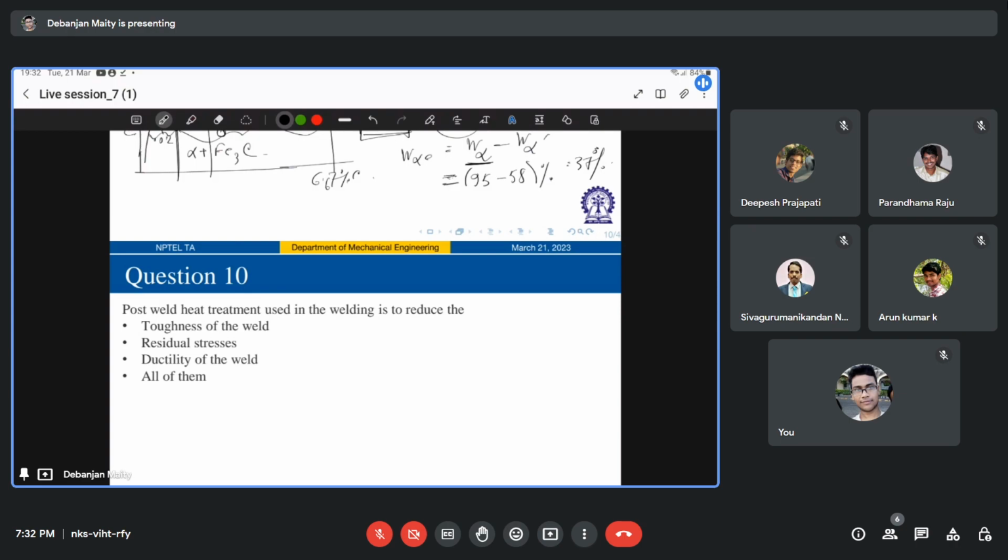Now what happens during post heating? I have already told that it can decrease potential hydrogen induced cracking, right? Hydrogen induced cracking typically occurs when the weld has a sensitive microstructure, or a high level of stress, or a sufficient level of hydrogen or moisture in the environment.